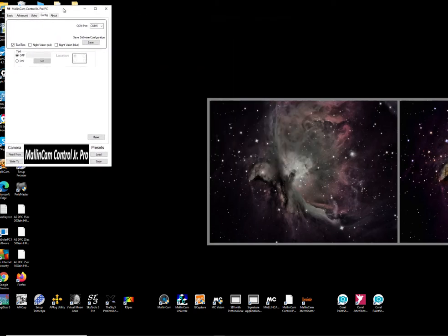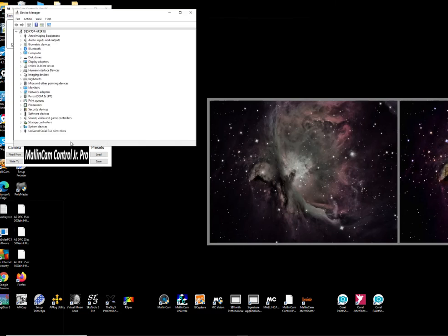Jose, I'm going to help you try to get your Junior Pro software configured. The main thing you have to find out is which COM port your computer control cable is set up with. If you right click on the little window icon at the bottom left and call up Device Manager, and then go to ports, you can see I have a bunch of serial ports.